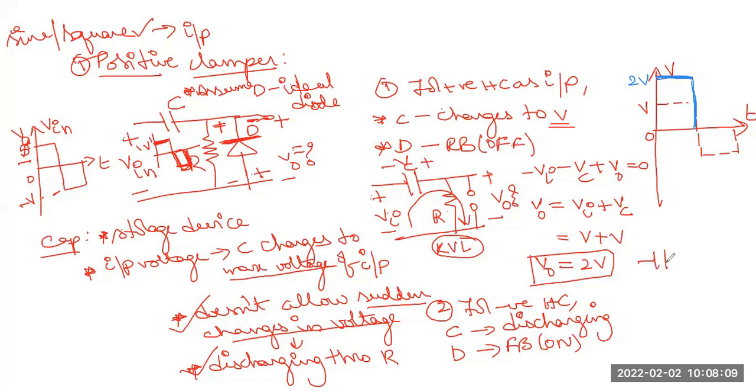Capacitance followed by resistance. But here the diode is shorted because it is in on state. Now, whenever we have anything in parallel to a short circuit, the resultant will also be replaced by a short circuit like this. So now your capacitor is not able to discharge because there is no resistive path, isn't it?